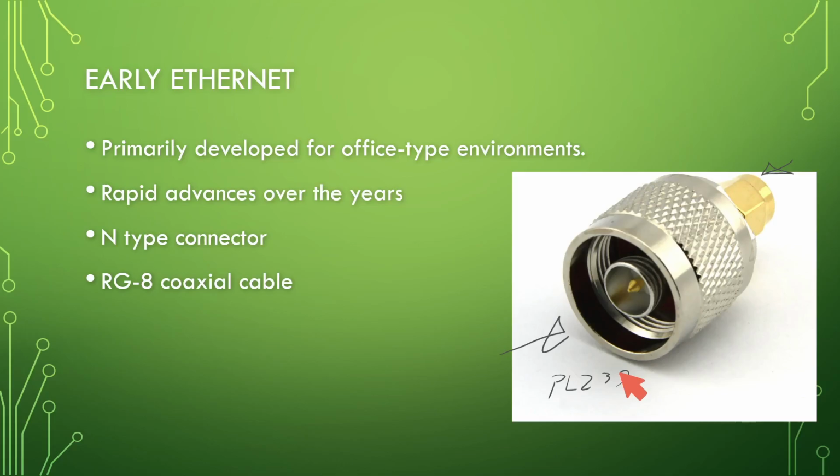RG8X, it's RG8 back then. We still have RG8X nowadays. A younger sibling, I'm going to call it, would be the RG58, I believe it is. So a little bit of give and take going on there. Coax sucks because there are hundreds of different versions of it. You've got the RG58, the RG8X, you've got the PL this, you've got the Flex. Are you freaking kidding me? RG6. RG6 is what most of the coax in your house is. For your TV signals, if you have coax in your house, most likely it's RG6.